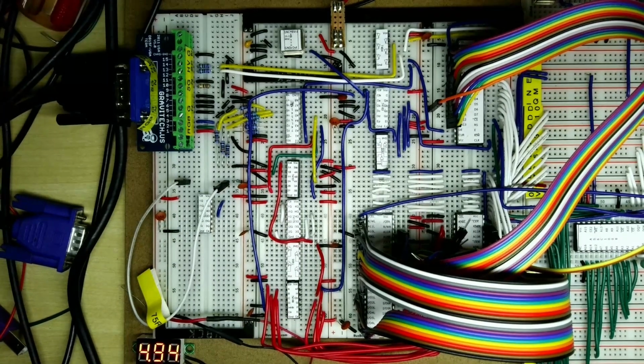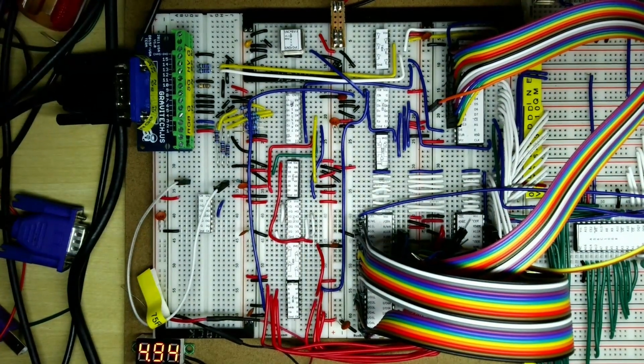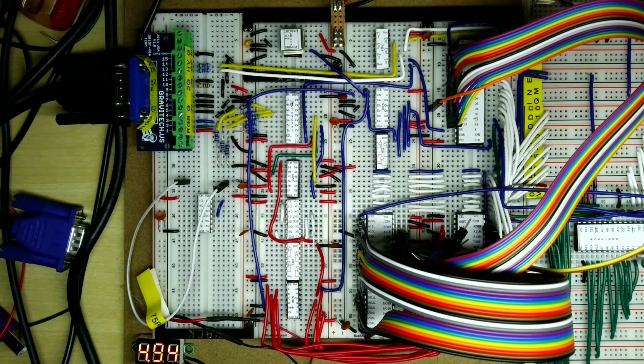You should also be able to see down the bottom here I've got my mini voltmeter on the last breadboard, and it shows 4.94 volts. So this is right down the end here. We've got a power rail just up here, but it goes to show that when I was doing some of my early video card, when I actually checked, I found the voltage down the far corner of the card could be about 3.6 volts if I wasn't careful.